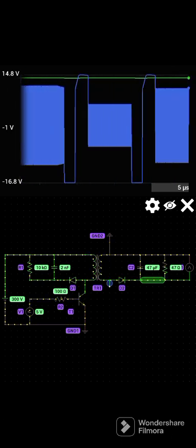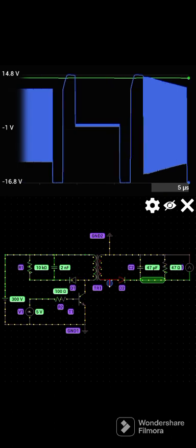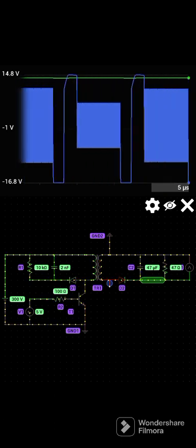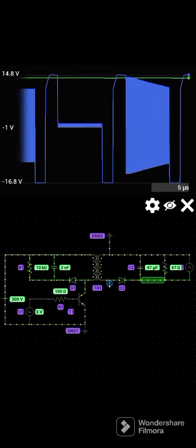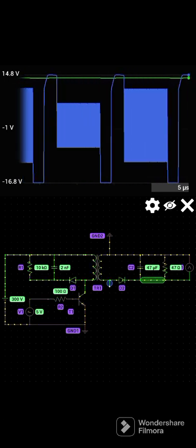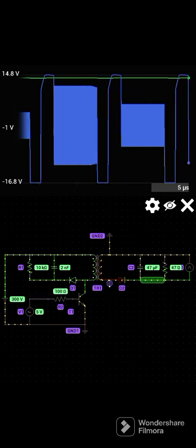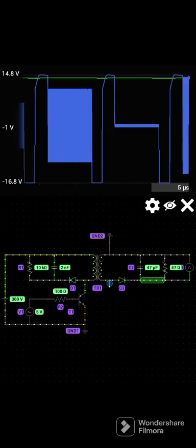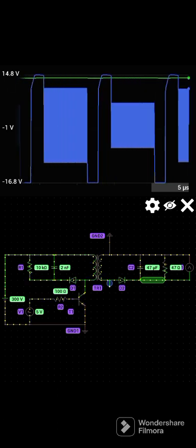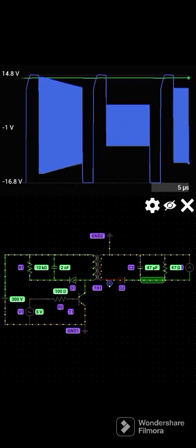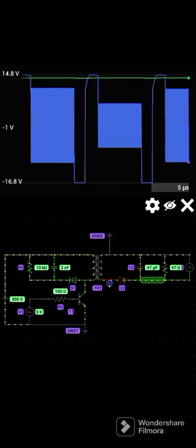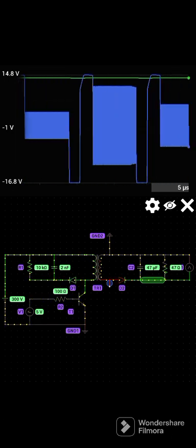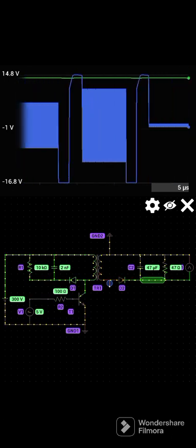One of the main disadvantages is that the transformer can induce significant leakage inductance, like the transformer can leak, which can cause high frequency voltage transients and increase power loss. Now look at this. This is switched at a very high frequency, and if it leaks, it's a big power loss, because of frequency and power, you can understand what I'm saying now.